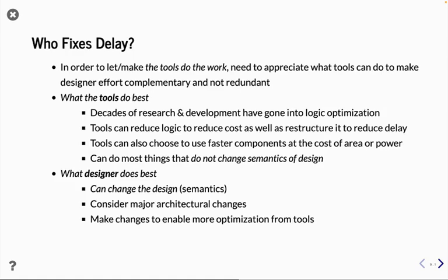The thing they can't do is change the semantics of the design, right? So if you have Verilog that says this is a certain behavior, and that Verilog, for example, could be produced by Chisel, it's obligated to produce hardware that mimics that behavior. So, if the result comes on cycle 2, it has to make a circuit that produces the result on cycle 2. It can't make a circuit that has more cycles, right? It can't make a design that takes 4 cycles rather than 2. That's not something tools can do normally.